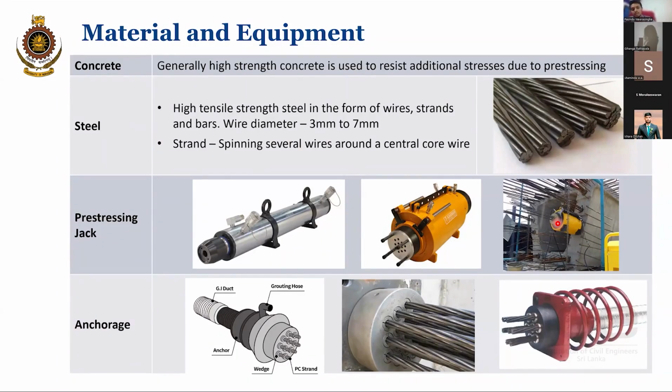But it has better performance than that. Even if it were expensive, you can't take it out once the concrete is hard. So the duct, we are not taking out anyway. But if the strand is losing the pre-stress, we can remove the strand and insert it later and jack it after that. That is possible.